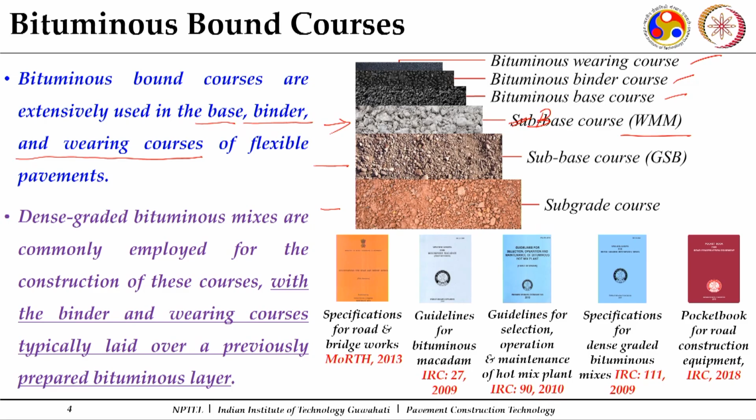So, dense graded bituminous mixes are commonly employed for the construction of these courses, which involves bituminous base, binder and wearing courses. The binder and wearing courses are the top two, the ones which are laid over a previously constructed bituminous course.